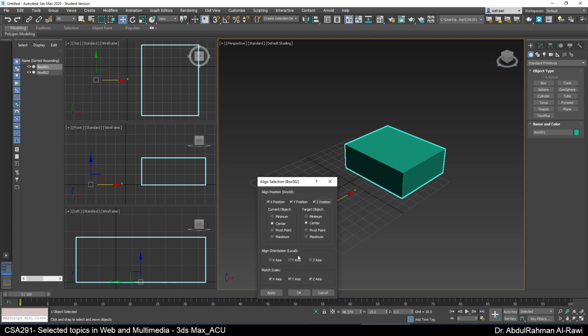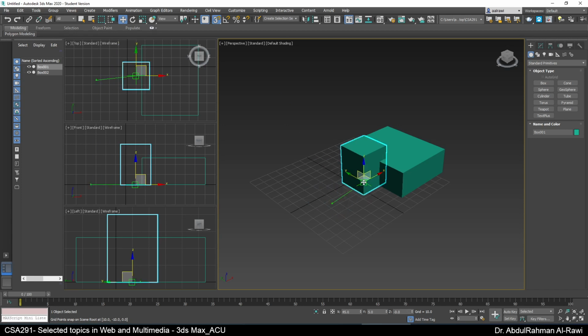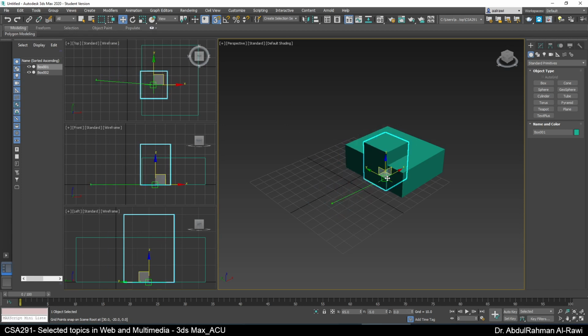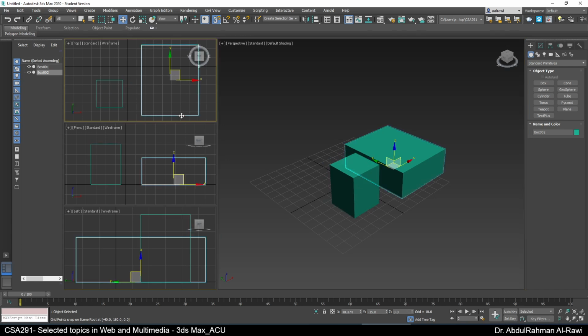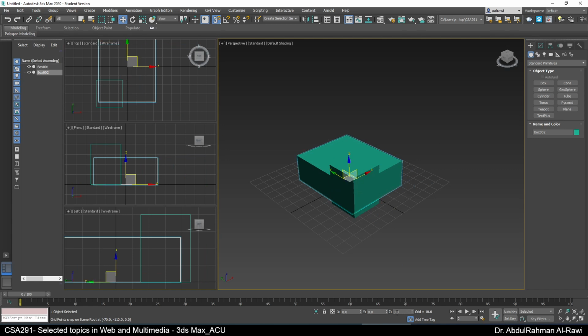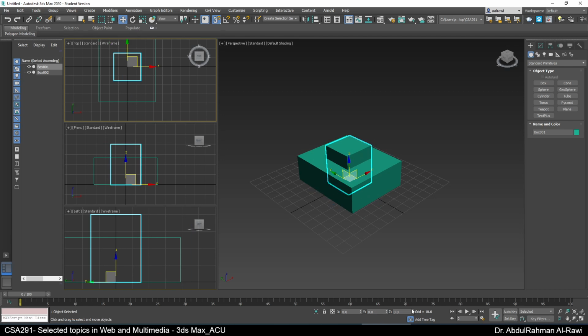It's a very, very powerful tool, very useful tool. Although you can use snapping to move it to them, especially with move. You can press S and say, okay, I will move it like this. They will be aligned together. Of course, if this is already aligned, let me just go to 0, 0, 0. And this, we can go also to 0, 0, 0.